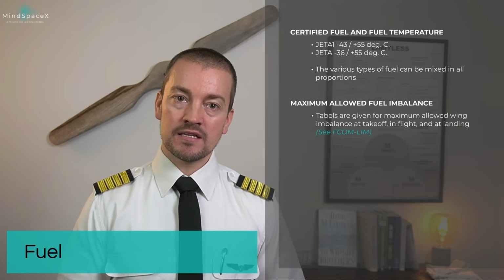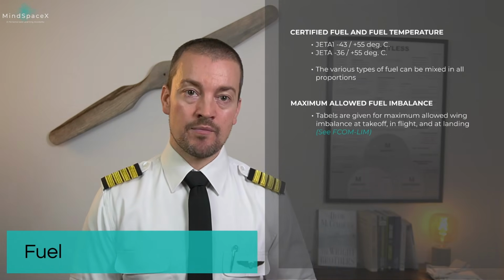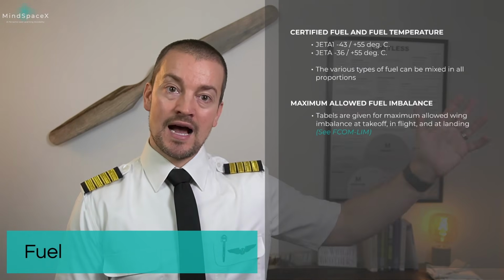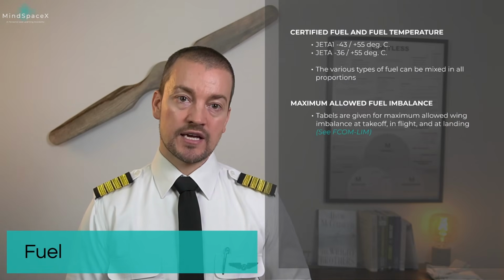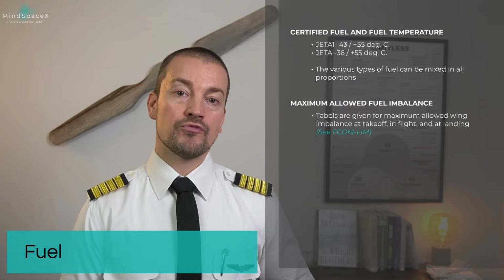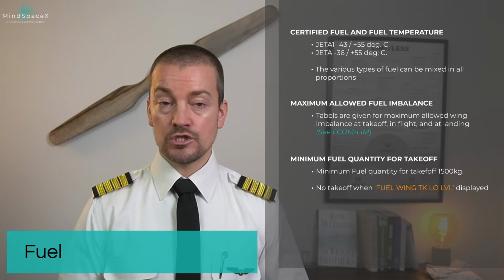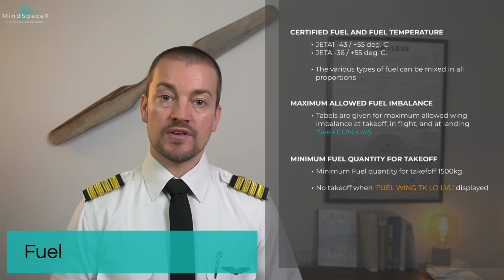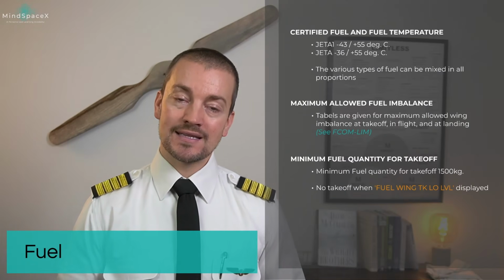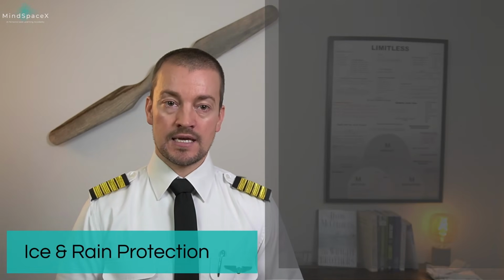Maximum allowable fuel imbalance depends on the fuel system configuration, the use of auxiliary tanks, the use of and capability of the wing tanks, outer and inner. Therefore, the imbalance should be checked with the appropriate manual for the aircraft you fly. Refer to your FCOM. Minimum fuel quantity for all aircraft is 1,500 kilograms, and no takeoff is allowed if fuel wing tank low level is displayed on the engine warning display on the ECAM.